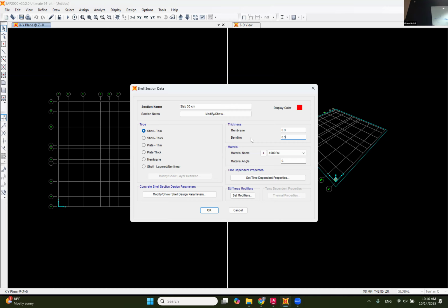For a slab, we also have that. That's true. That's why we're putting 0.3 for the membrane, or that can happen. Well, we usually put it just as an effective thickness of the slab. But for the slab, there's something called rigid and flexible membrane. So usually when we assume a slab is rigid, that means the slab cannot do this action.